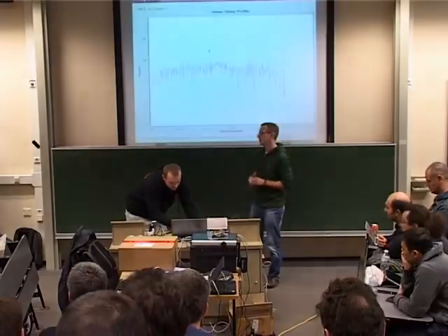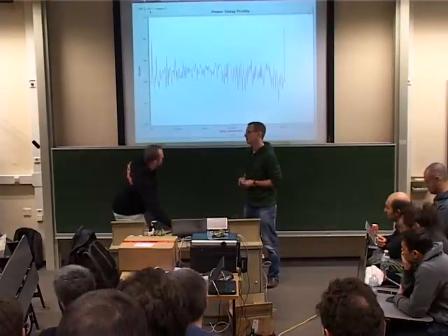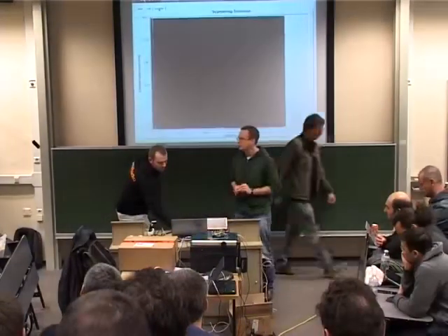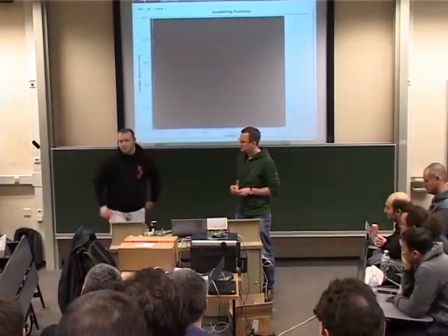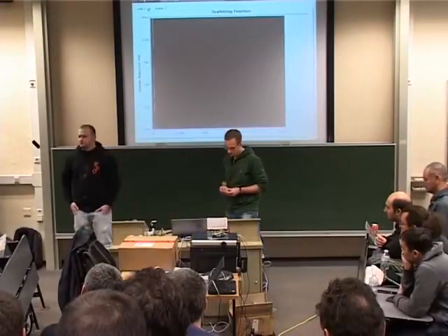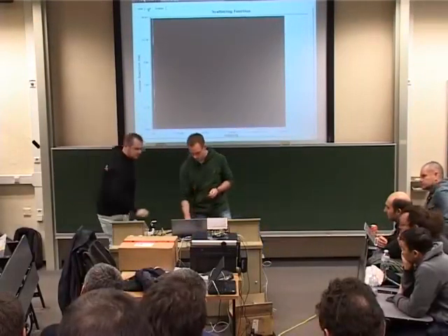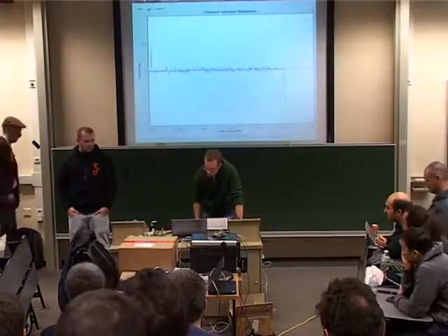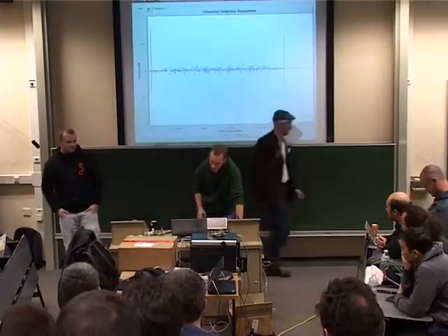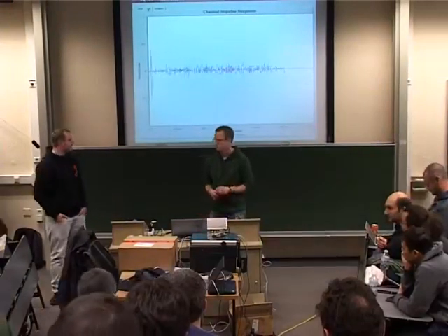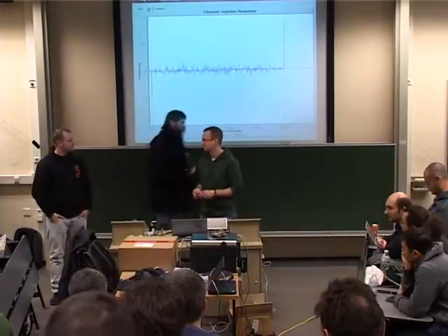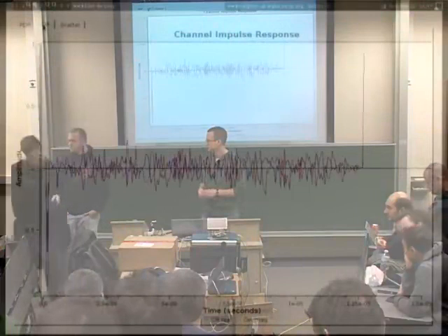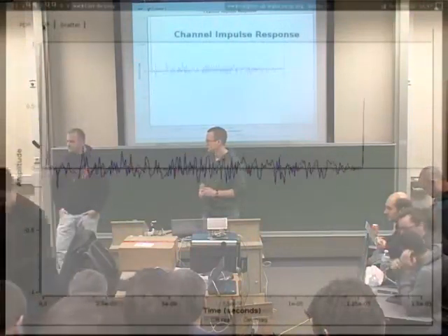But there is a GNU Radio channel block that does the drifting. I'm pretty sure about that. Yeah, you can add the drift. So the idea with the hardware is that they would resync. Usually there's a pulse-per-second input, so you are constantly resyncing to the GPS signal. Plus or minus reality, you're within pretty good spec. The two are going to be pretty much locked together based on that. And then you have your other hardware or your channel models that you add your own frequency drift to. We now have it where your timing offset can be dynamic as well.